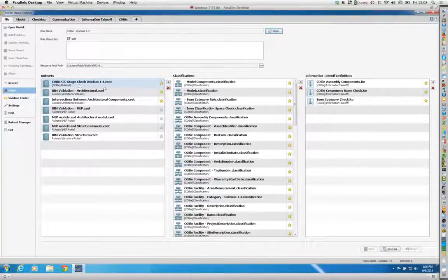And then underneath that, we have initially the architectural BIM validation set, which is the default one inside Solibri. Again, you may need to configure it or do things with it. And this checks obviously the intersections between architectural components. As the project progresses, and you obviously include the different consultants' documents or components into the model, then you can run the BIM coordination-based rule sets that come from Solibri. And again, I've left those as default, so you might want to configure those and change them to how you actually run them in your own offices.